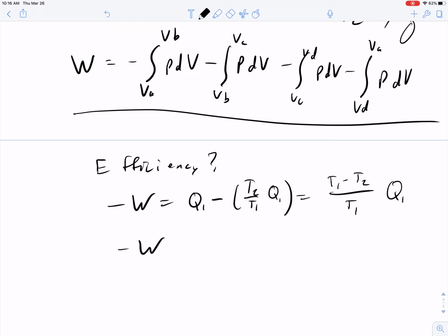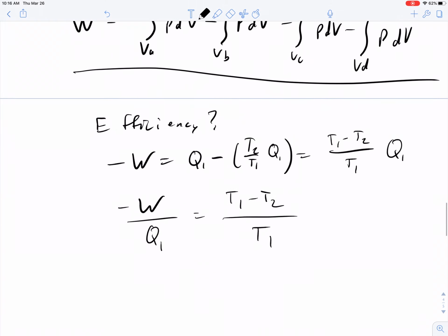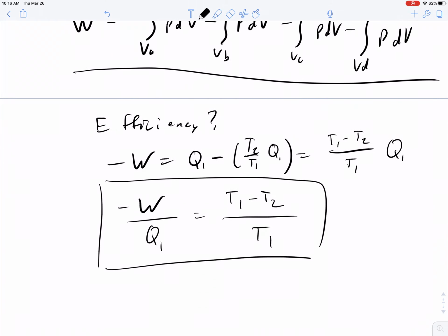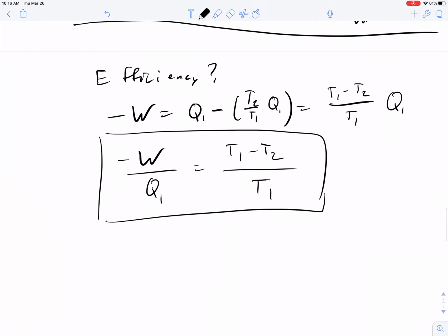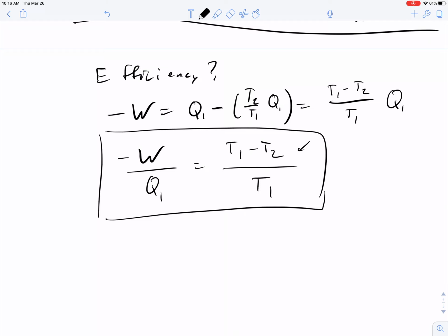So the Carnot engine is, at least conceptually, one way that one could design a piston-driven engine to extract work from a thermal fluid, a working fluid, if you have all of the conditions of absolute no friction and everything else. So here the work that you expect is equal to the temperature difference between the two thermal reservoirs and the heat transfer that you put in through Q1. But this is, again, an upper limit. It's a maximum theoretical efficiency for an engine.